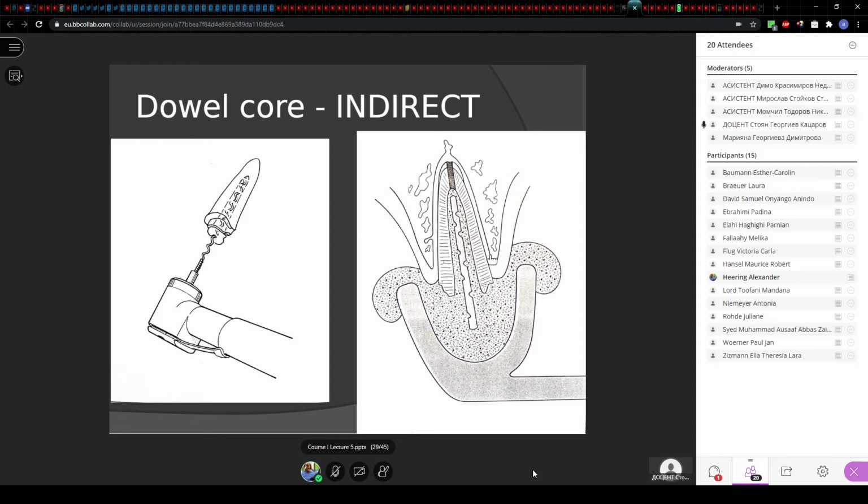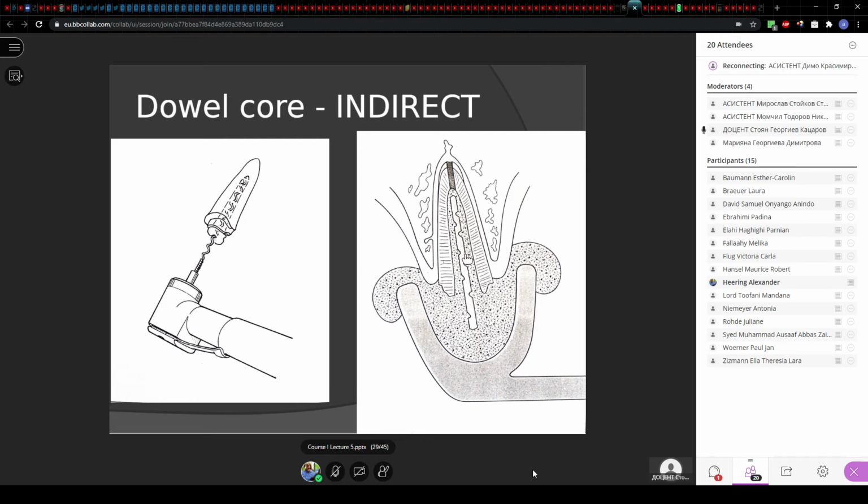So if you have a silicone that has greater than 65 hardness according to Shore, you can just skip this part, because sometimes it's much more difficult to align this post when it's there. So in most cases, it's always preferable to do it without it.